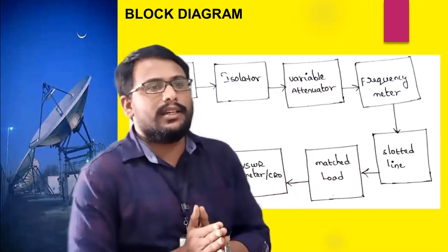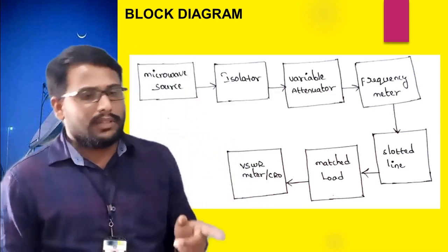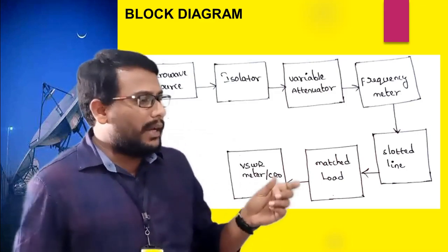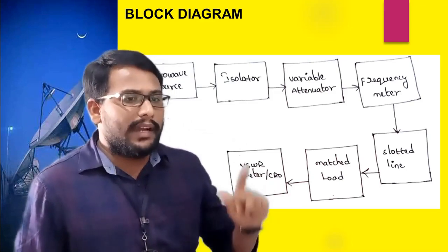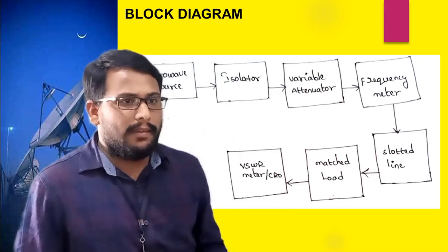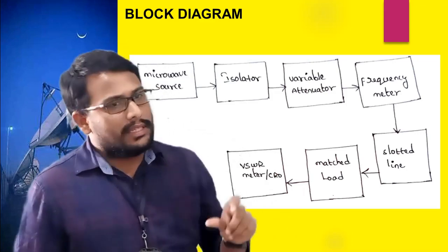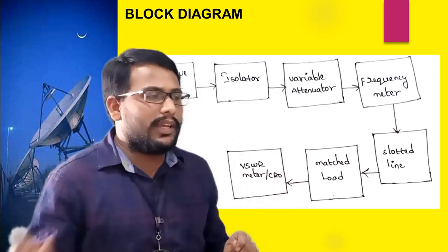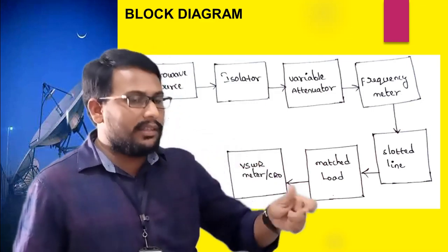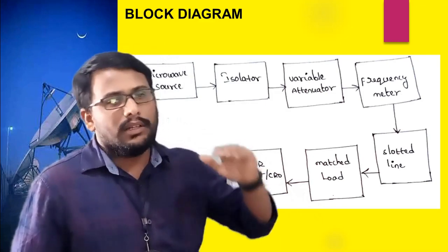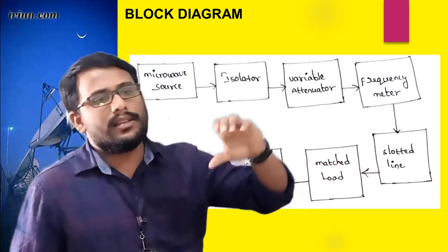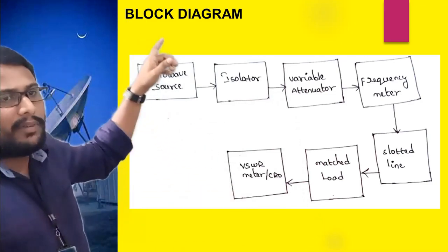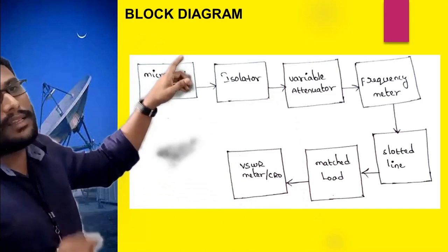After that, rotate the repeller knob. By rotating the repeller voltage knob in the anti-clockwise direction, we have to fix the maximum signal strength that appears on the CRO.